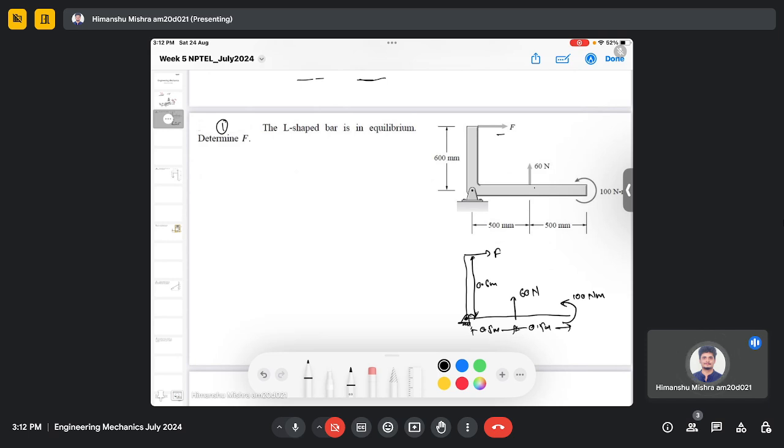Then we assume some virtual displacement, that due to these active forces the bar rotates, and it will rotate like this. So it will rotate by angle del theta, and here it is del theta. Now we need to find this displacement. The displacement will always be length multiplied by del theta.